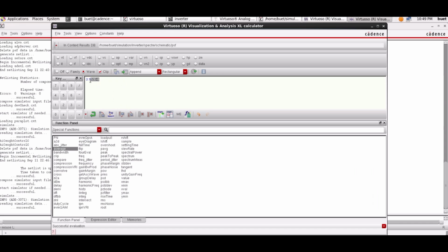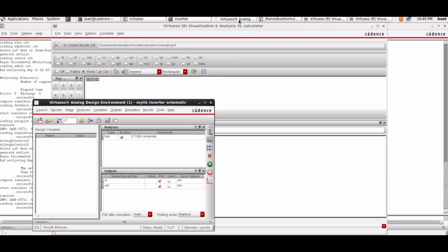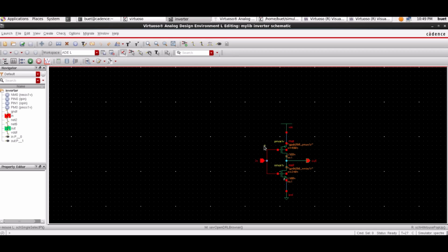And that's a wrap for this lab. We have covered a lot today, from setting up Cadence Virtuoso, creating an inverter schematic, performing transient simulation, and analyzing power and delay across different corners. These are foundational skills in VLSI design, and you'll be using them throughout this lab series.